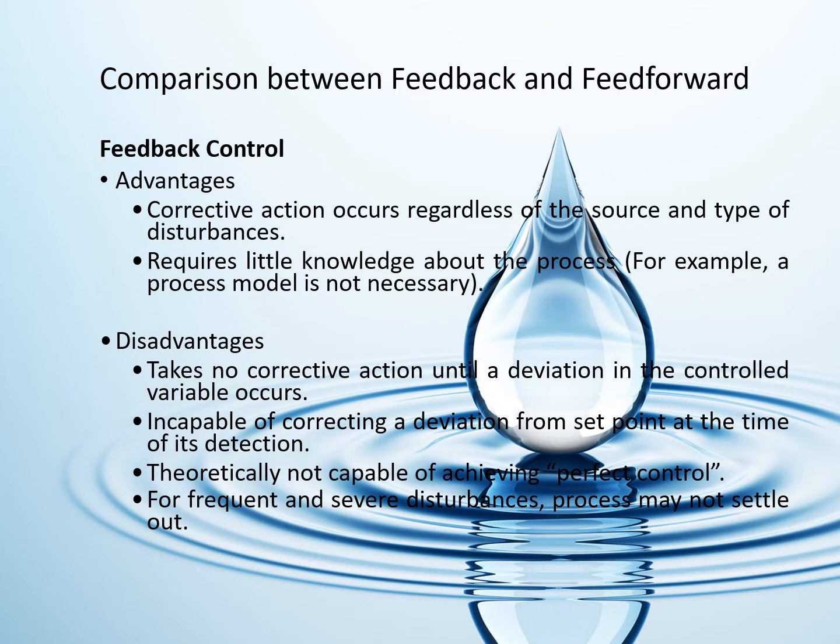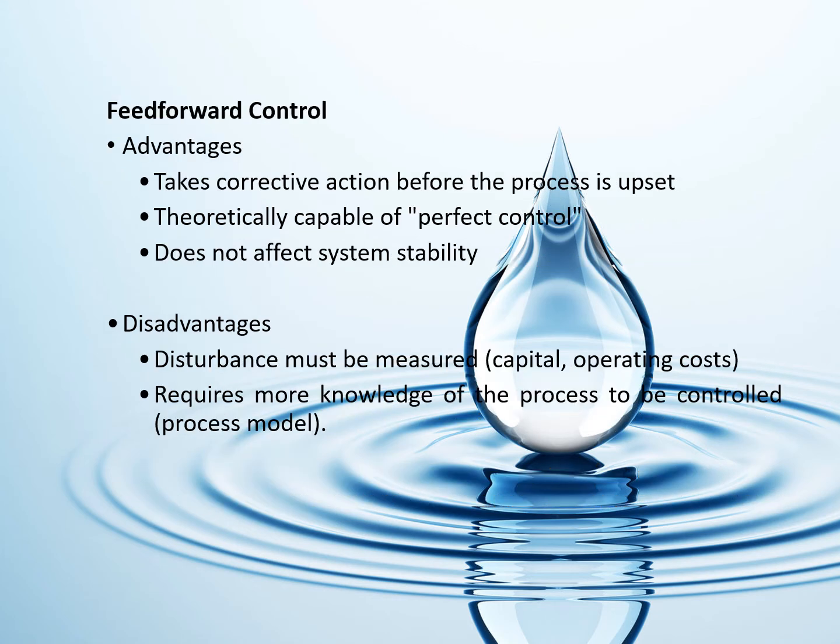And the other disadvantage is for frequent and severe disturbances, the process may not settle up. So for the process with a severe disturbance, it is better to use a feed-forward control. Okay, now I move to feed-forward control.